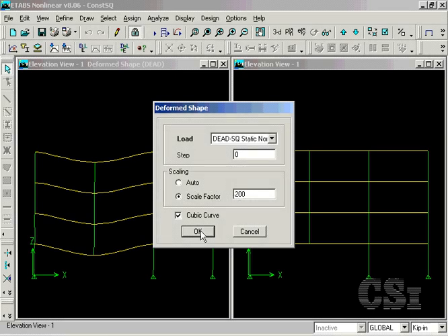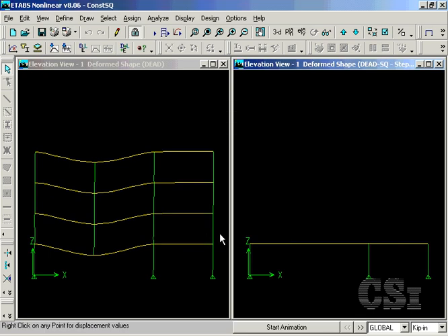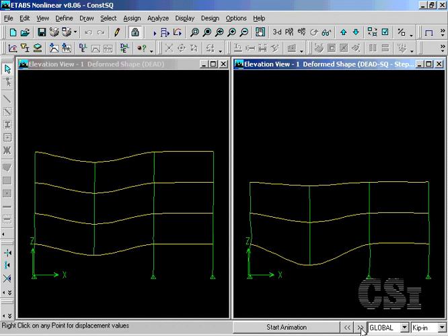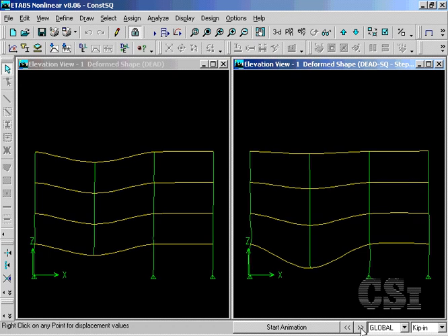We set the scale factor to 200 to match that on the left. Starting with step 0, the first floor undeformed, we can toggle up the construction stages. Note how the displacement at the transfer girder location grows significantly larger than that of the model where no sequential behavior is accounted for.